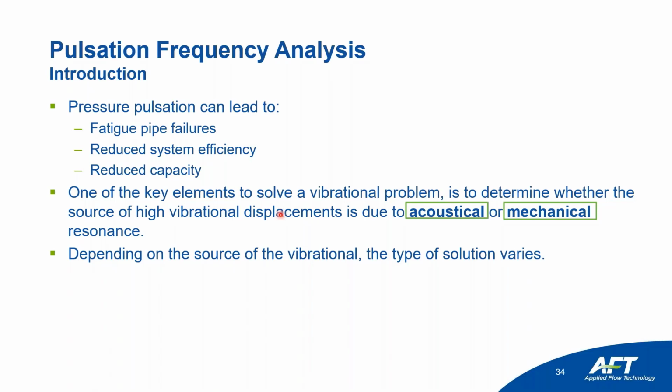Some supports like U-bolts do not constitute a dynamic restraint for the pipe, and that allows the low frequency modes to appear. And as we know, low frequency modes require low energy to be activated, and hence you can see high displacement in the system. Another mechanical solution can also be changing the location of your supports.